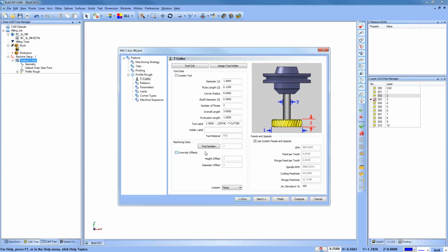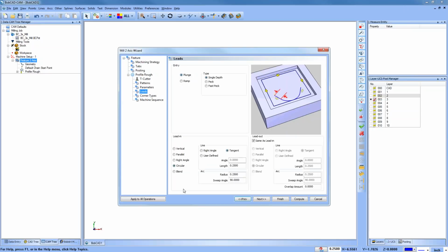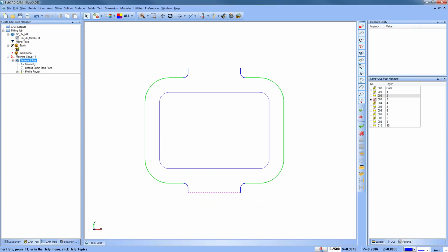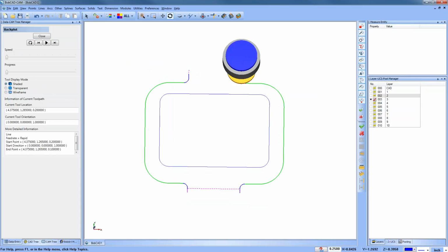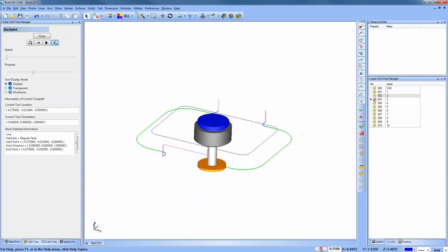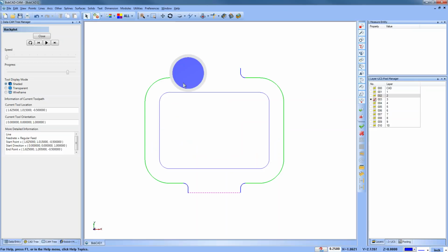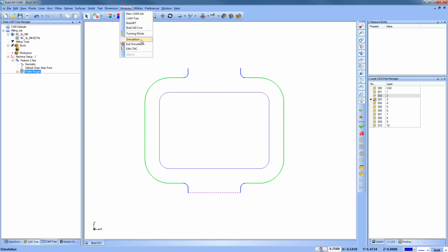All right. So there's going to come times where you guys may need to do some undercutting. Okay. So that's what we're looking at here. We have a T cutter. We want this T cutter to come in, and it's doing an undercut throughout the part. Let me see. I don't know if I'm gouging on my lead in. I may need to extend that. So let's take a look at the simulation.